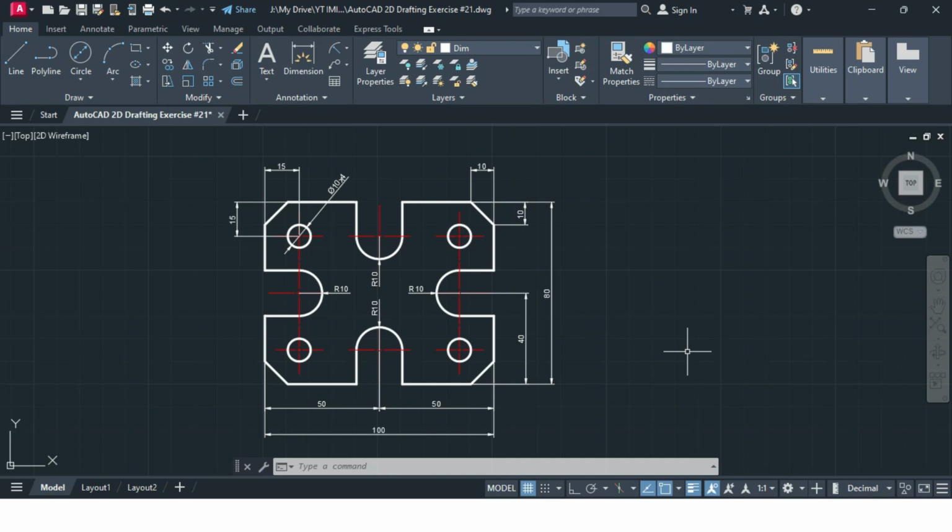In today's video tutorial, we will study how to prepare this geometry in AutoCAD. As usual, we'll first spend some time studying this geometry and trying to see how we'll proceed with the drafting. After observing this drawing, I feel that the best way to start is to make a rectangle of 100 units by 80 units.